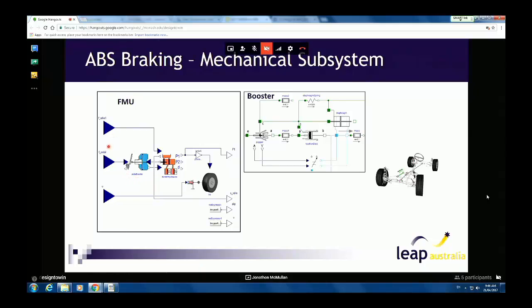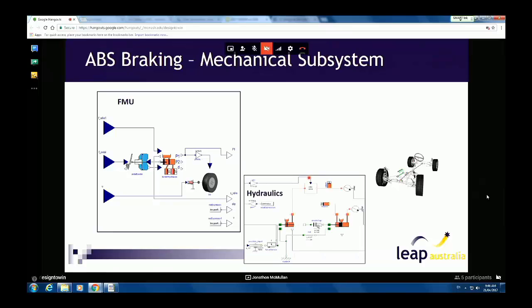So we go and add a number of inputs to this and a number of outputs. And then within each of these, we have their own subsystem. And so you can add as much or as little detail as you like, but they're always lumped. So here we have a diaphragm spring here. It's just this one element. We have some extra mass attached to that. We have some more custom models for things like reaction disks. And then we have some valves as well. So adding one more expands the hydraulic system.